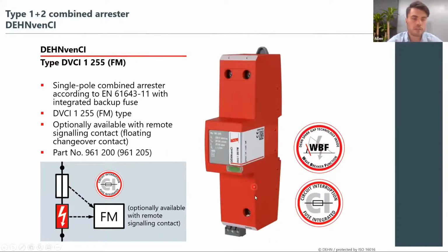Some of our modules do have the FM contacts, which is a remote signaling contact, which you can wire any way you would like. You can light a light, or you can put a buzzer to know that the SPD has actually failed.